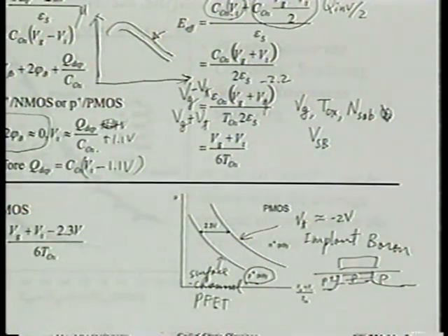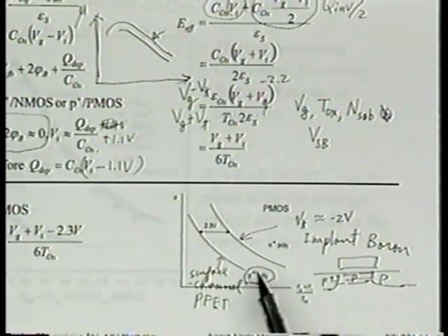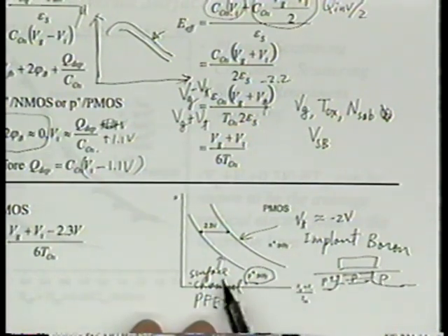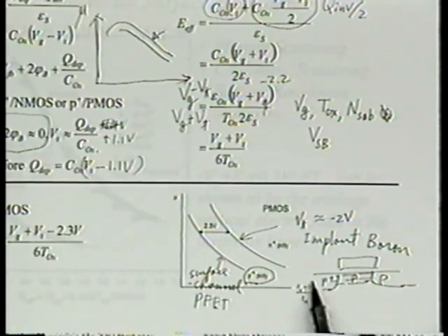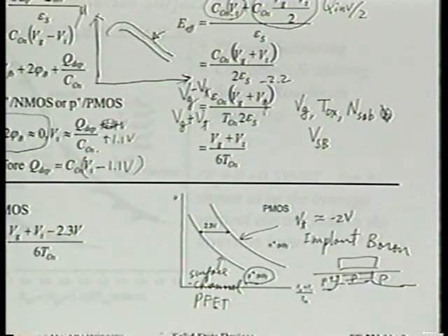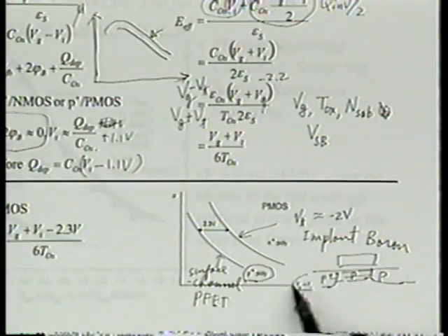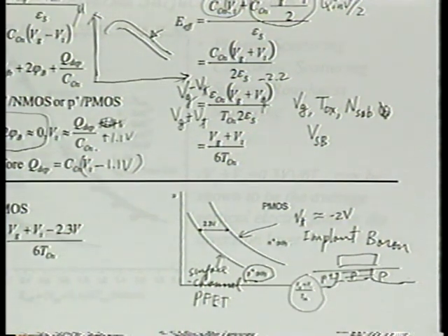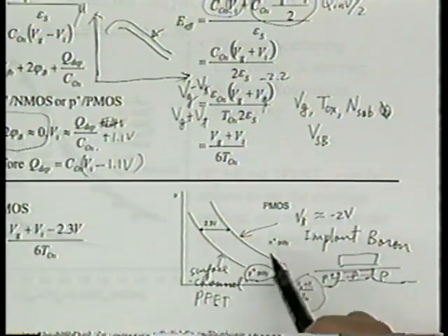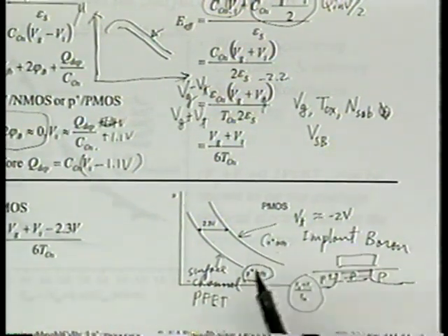And I believe because of this misnomer, there's this misconception that with N plus poly the current flows in the subsurface, in the bulk, partly because of this data. It's well known that if you design 2 transistors, one with P plus poly, one with N plus poly, you manage to get the same VT, right? Of course, one requires implanting boron, one implants phosphorus maybe. And you measure them at the same VG, and they have the same oxide thickness, which really means identical conditions. You see what I mean? Same VT, same VG, same oxide. It's well known, has always been known from early on, that the N plus poly design gives you higher mobility.